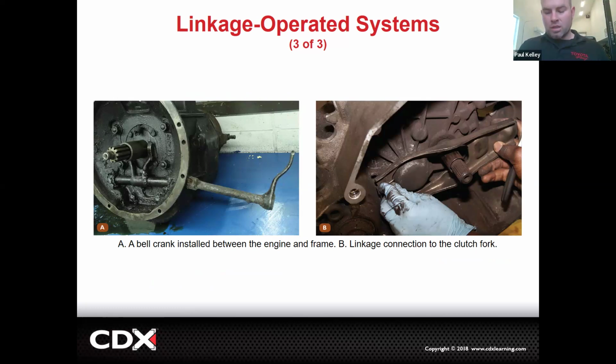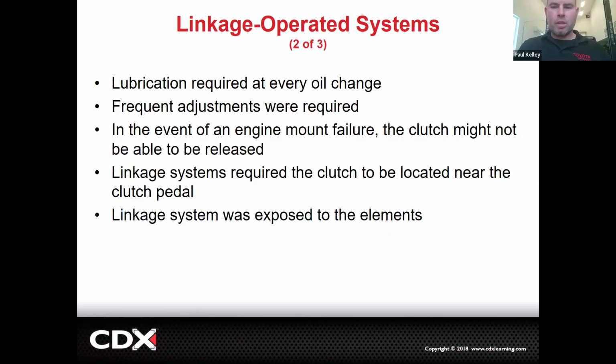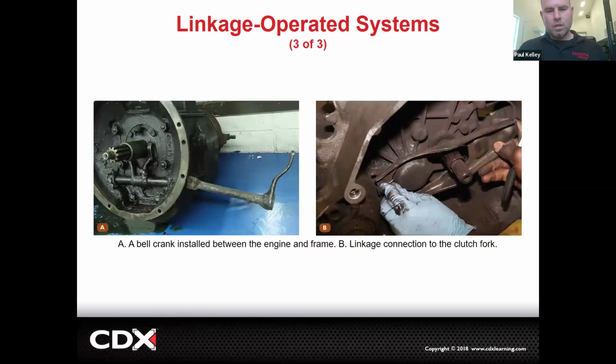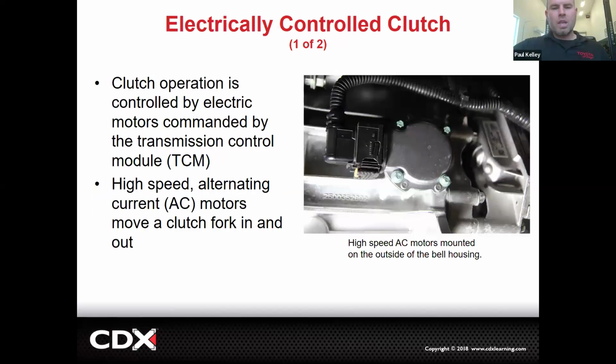So you'd be lubricating the chassis, the steering parts, the clutch part. We were doing a lot of grease. That's why we were grease monkeys. We'd be greasing all sorts of baloney. Then the cable was less maintenance, and then hydraulics is even less maintenance than that. Self-adjusting and everything. Cool. So it's a little bit about linkage.